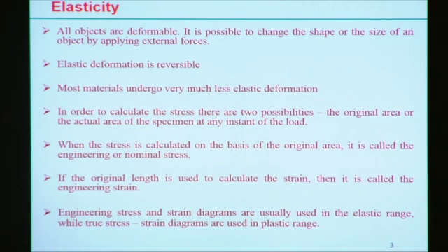Of course, the engineering stress and strain diagram is specifically useful within the elastic range, but the true stress strain diagram is specifically important in the plastic range. Although for small deformation, between engineering stress strain and true stress strain, there is a very small difference within the elastic limit.